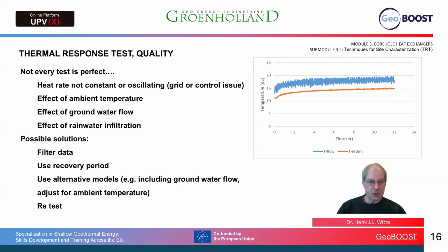Now, there are some solutions. We can, for instance, in the case here, filter the data or use the return temperature and not the injection temperature, because the return temperature is much more stable. We can use the recovery period. So after we turn the test off, the temperature will, let's say, recover to the natural temperature. Then we won't have any issues with control or power grid anymore. And we can try to analyze that part of the data.